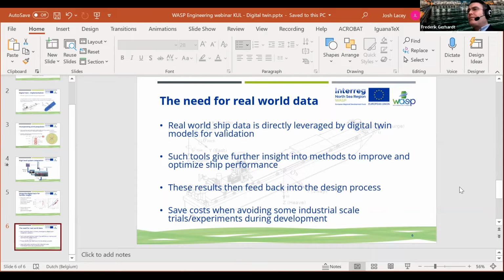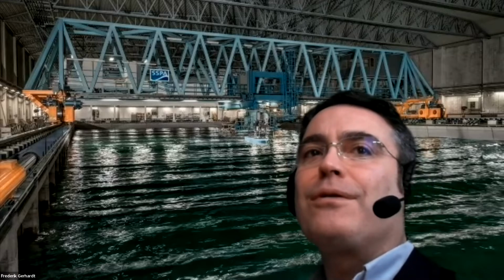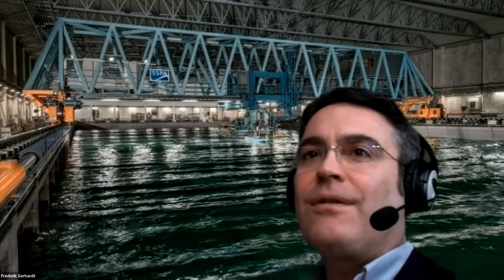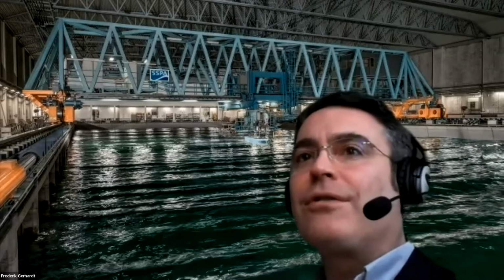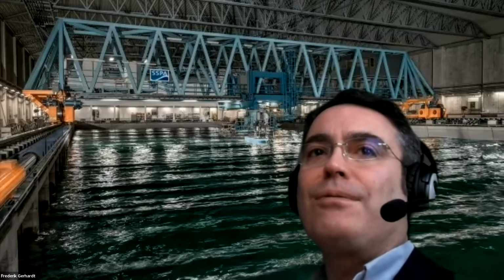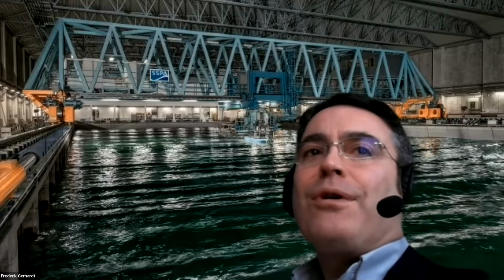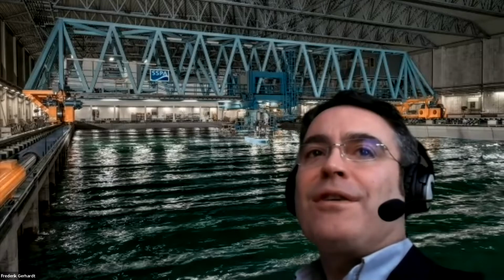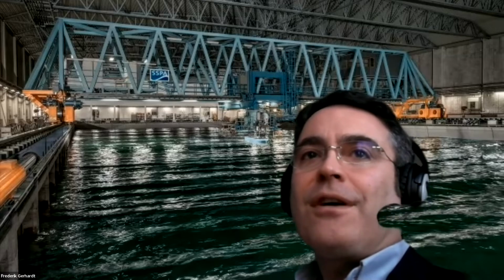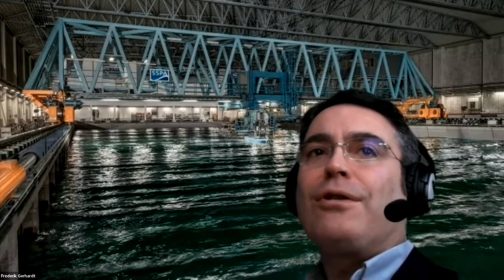I totally agree with what Josh has said, and as you pointed out, some of the layers might get more lightweight in terms of how they're modeled. Once a ship is in operation, instead of the CFD or even the lookup table, you could also start to collect historical data and then take a sort of machine learning approach, where you say, under those conditions, wind direction so and so, I used so and so many tons of fuel per hour last year. Am I better now or not? And what were last year's settings? So you start building up an operational historical database.